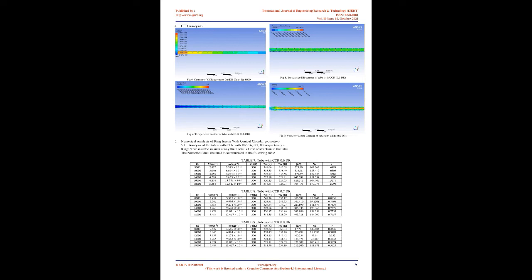Each case must be initialized before the Fluent code begins iterating towards a converged solution. In this study, the option chosen for initialization was to compute from inlet zones. The number of iterations ranged between 800 to 12,000 depending on the case being run and how long it took to converge. Iterations were performed with the default under-relaxation factors for all parameters.